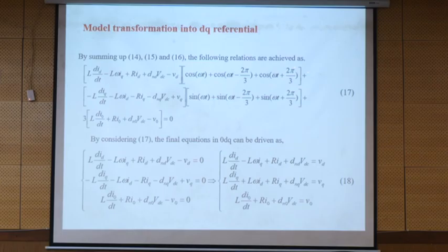Okay? And then in the second part, L dIq/dt in the q axis, times 2 sine, and at the end also for the homopolar value we have this. So if we get back to this, it is equal to 0. When does it happen? It happens when this value is equal to 0, this value equal to 0, this value equal to 0.